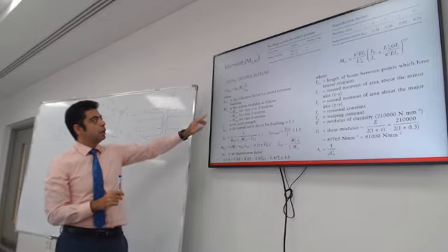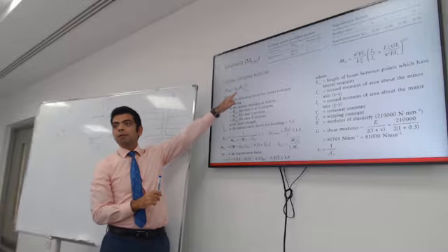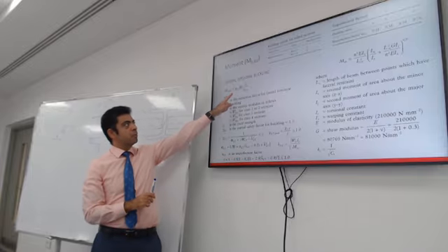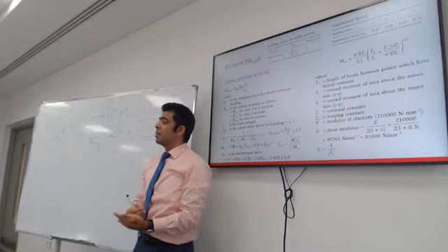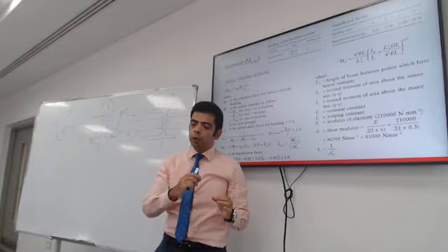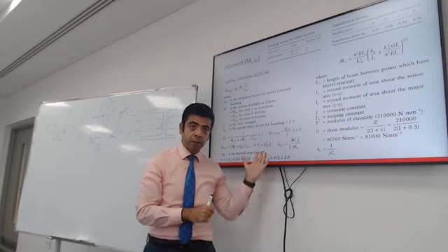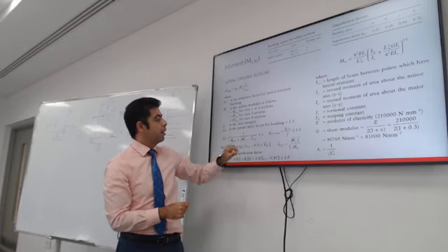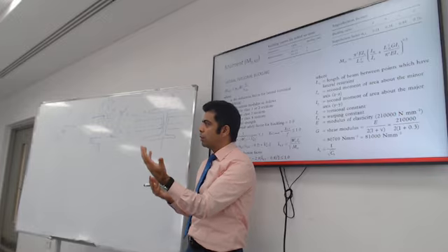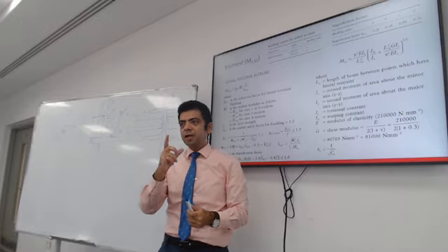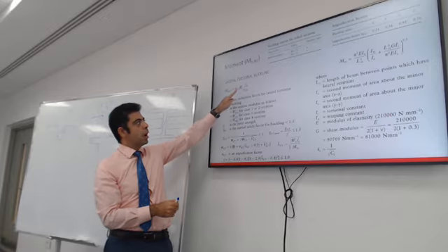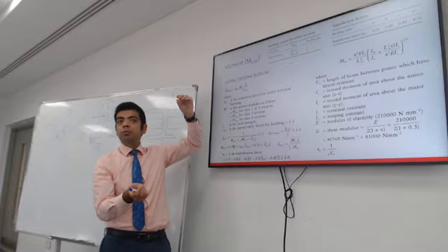Okay, so that will leave us with the reduction factor for the lateral torsion buckling, and all these equations just to get how much we reduce the capacity of the section. The exam is open book, so you can work your way through the steps to calculate these factors and have all the equations you need. So you have a process. You understand what you need. I need the capacity of the section in moment. All right, that's the equation. Most of the factors I know, I will just need to spend some time to calculate the reduction factor.